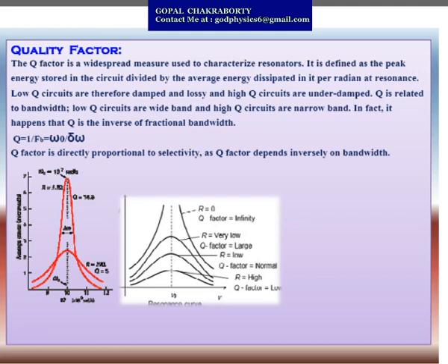So you can write the quality factor as the ratio omega naught by delta omega. Delta omega is the frequency bandwidth, equal to omega 2 minus omega 1, where omega 2 and omega 1 are the half power frequencies. Half power frequency means where the power is 1 by root 2 of the maximum power, or 1 by root 2 of the maximum energy.